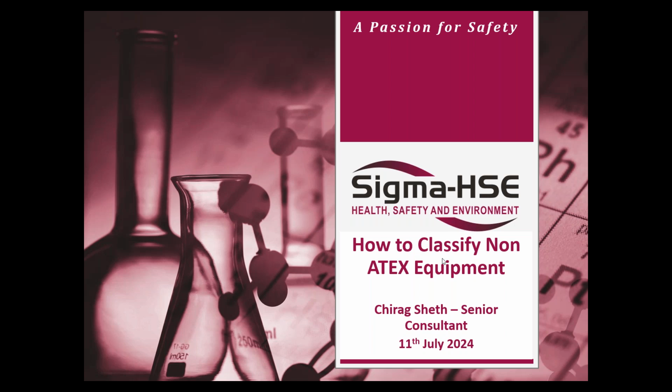Okay, good afternoon everyone. Welcome to this webinar on how to classify non-ATEX rated equipment. Today we'll be dealing specifically with the procedures and the assessment methodologies commonly referred to as non-electrical equipment ignition risk assessments, referred to as a NIRA. It is a way to achieve compliance for non-ATEX or legacy ATEX equipment.